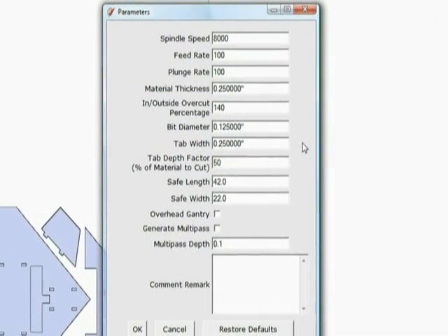And it's very important to have these parameters set where you like them, because this has a bearing on the machine instruction. We'll first start off here with spindle speed. Now, most of the guys that are using the PhlatScript just don't fool with this. Spindle speed, 8,000, we just leave that alone as an arbitrary number. Now, as we advance with higher level CNC machines and so forth, we will certainly want to maybe experiment with that spindle speed. But right now, we just leave it alone at its default value of 8,000 RPM.